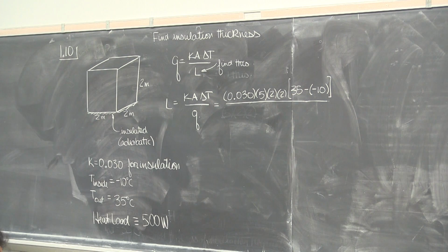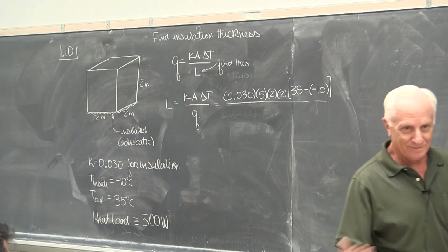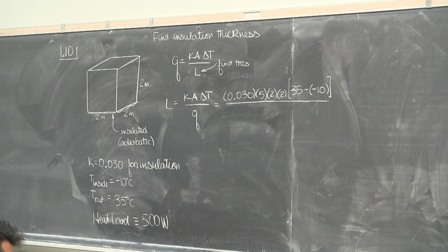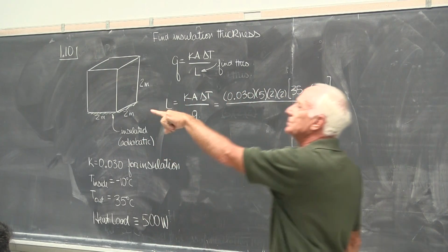What is heat load? When you take ME418, you talk about HVAC systems and how to design them. If that system went out in this room right now, no more air conditioning, how much heat's being generated in this room? Well, we've got 35 people times so many watts for each person. So we've got the heat load of people. We've got the lights. And if we had 32 computers in here, the heat from the computers, and the heat that comes through the windows.